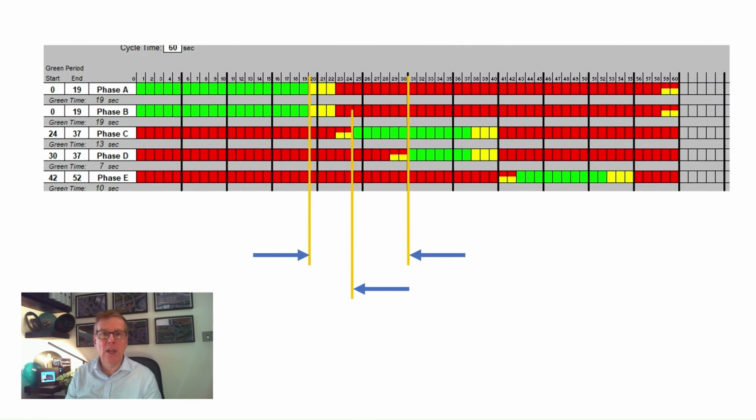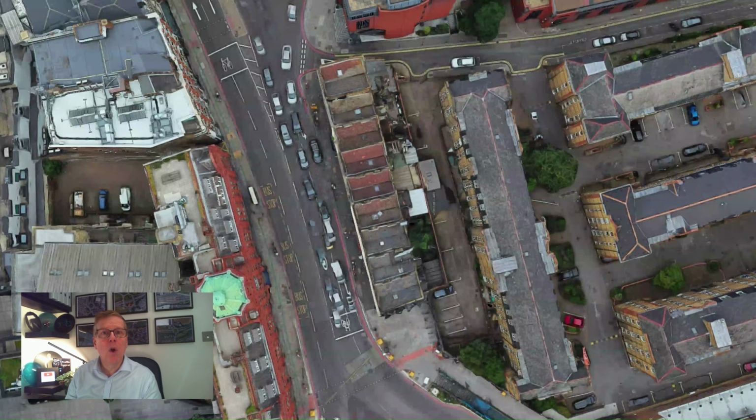The advantage of a phase delay is that because it is specific to a particular stage change, it won't unnecessarily increase the interstage period for other stage movements, so will minimize the impact on efficiency overall.